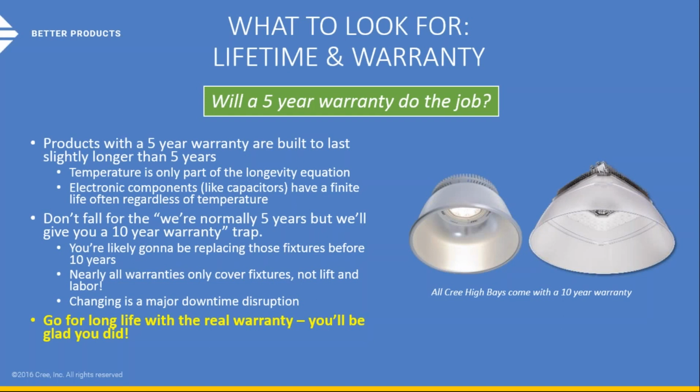When you buy a product, make sure the product is rated for the set number of years. Look at the details. Look at the design specifications. If the product is warranted for 5 years, then typically the product is designed to last you a little bit more than 5 years, and then after that it's going to degrade, probably beyond the L70 range that I mentioned earlier, which in most cases will require a replacement of that fixture. The lights will still work after 5 years, but just not at the adequate levels that you need.